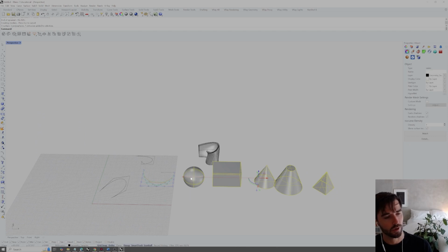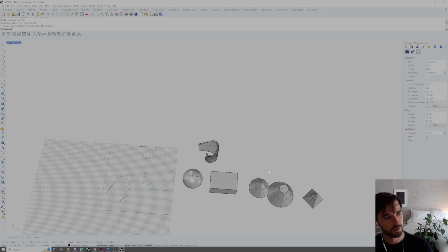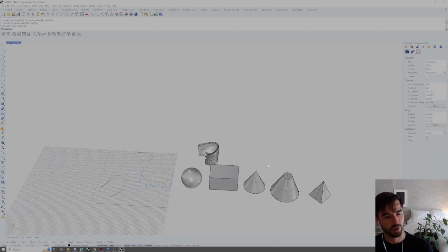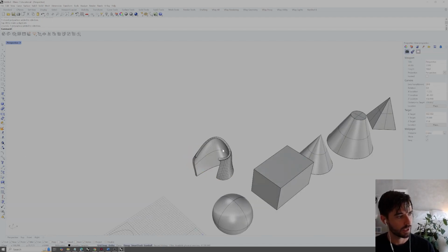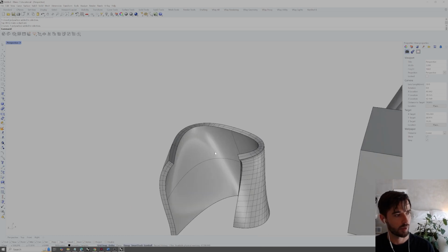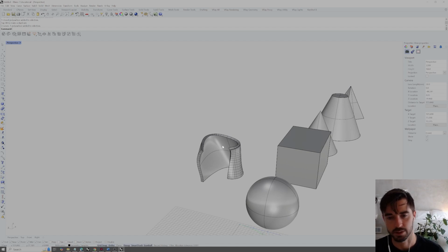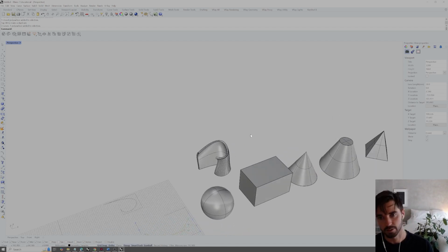So these are what are called platonics or primitives, which are mathematically defined base geometry types, versus the NURBs geometry here, which is defined by mathematically swept or infinitesimally calculated sets of surfaces, which are really just line or curve connections between lines or curves.